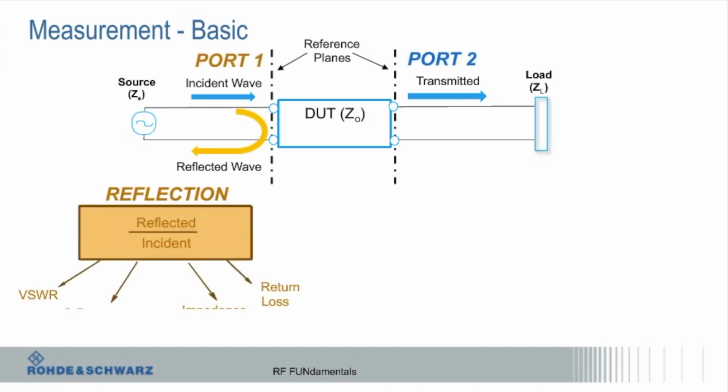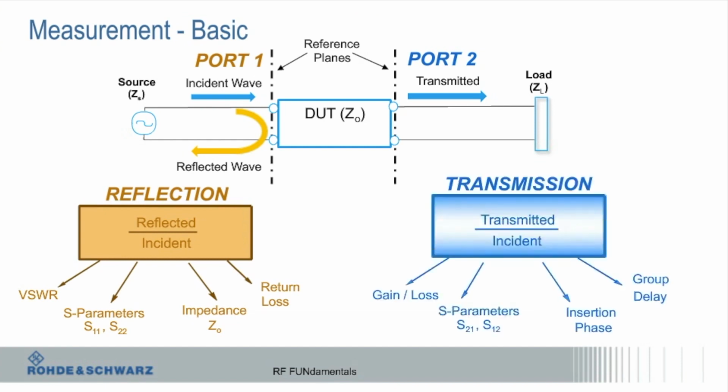Port 1 and Port 2. So this is all VNA stuff. Fundamentally, a VNA measures S parameters. Don't let anybody tell you otherwise. All the other stuff, it basically takes those measurements and manipulates them mathematically. After I do it, I get S11, S22, S21, S12. S11 is the reflected at port 1, S22 is the reflected at port 2, so obviously you see a mismatch anywhere. S21 is if I'm going this way forward, that might be the gain or loss of my device.